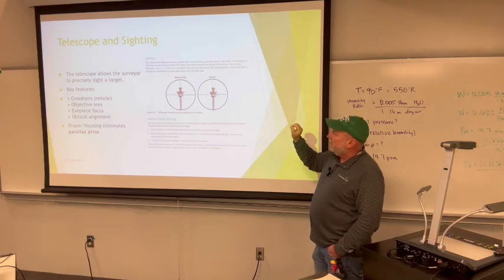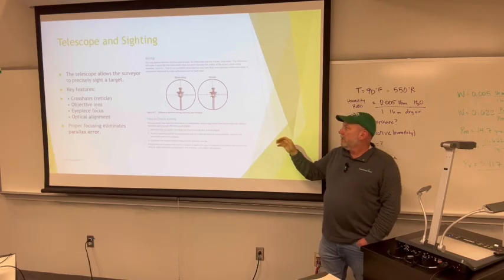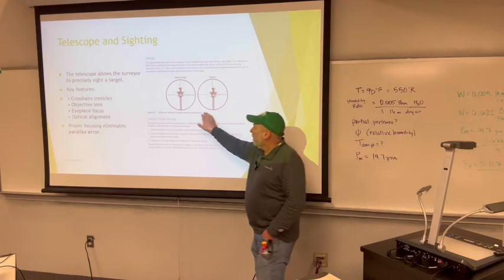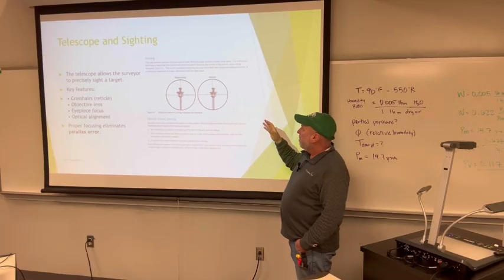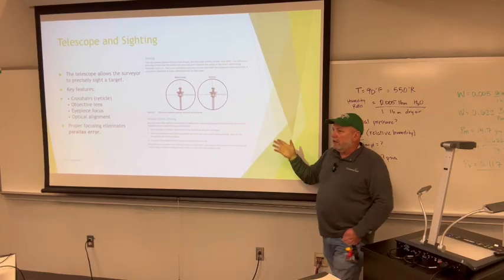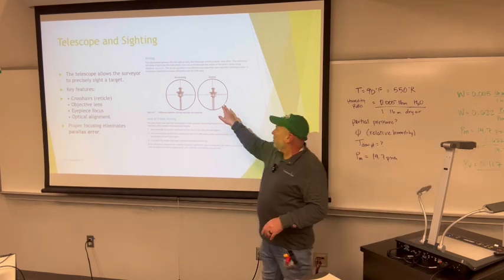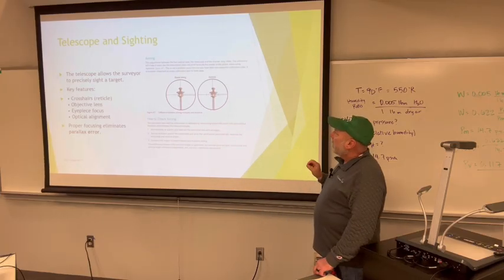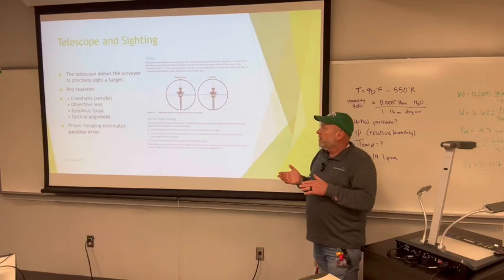This is really interesting to see, and I didn't realize this when I was out in the field, first starting out and first using these robots. When you manually turn the instrument to sight the center of the prism, you manually sight the center of the prism. Trimble has what they call auto lock, where it will automatically see and snap to the prism. And it looks like it's not snapping correctly. There's an adjustment that can be made to help minimize that offset.